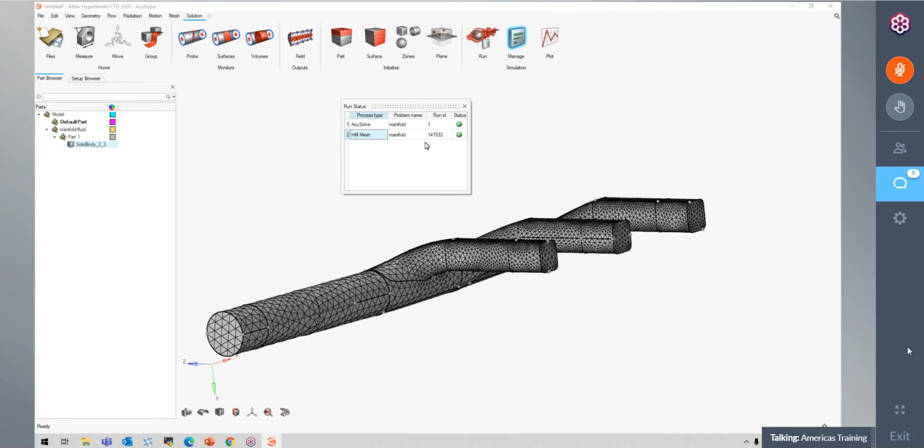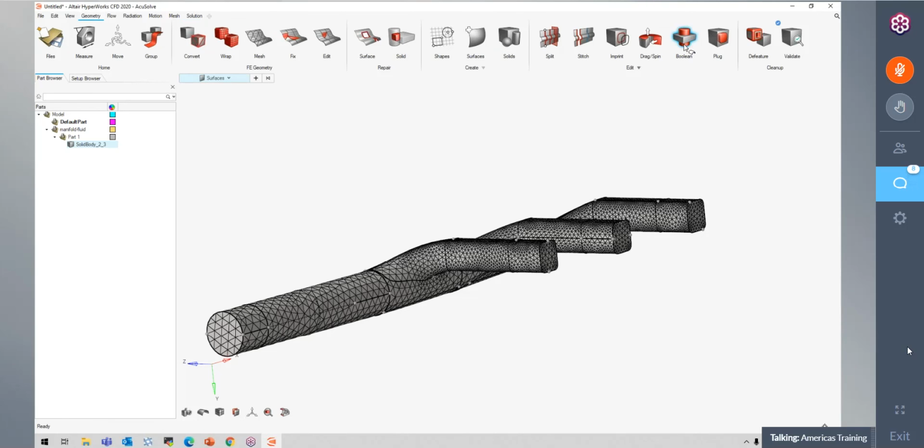If, let's say, you generated your model, you made a mistake, and you want to stitch it together, you can do that. That's perfectly fine. And for the most part, if you have the geometry in the model, you can use the geometry tools. So you can use these Boolean operations. That is probably the best way to do it. If they're volumes, using the Boolean, you see right here, it's even warning me that if I do any changes, it'll remesh. It takes a while to make changes to this.